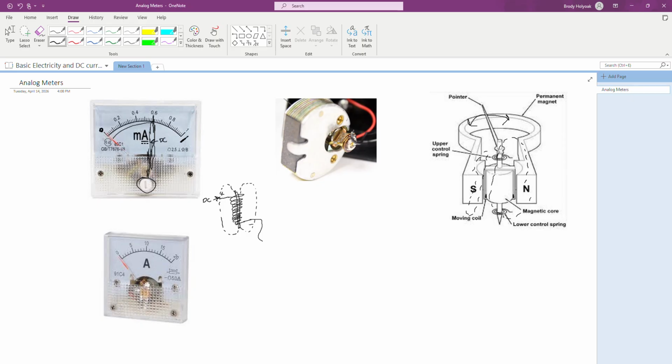And inside, it's kind of hard to see, but a lot of times they have a little post that sits right here to keep that needle from going too far. But what happens is physically we've stopped that needle, but if we keep putting more and more current through this, that magnetic field builds and builds and builds. And eventually this thing's going to try to rotate, and it's going to try to put the needle over here. But if there's a pin right here that stops it from spinning, eventually that needle or that arm, instead of looking like this, is going to start doing this. We're going to start bending things, and we're going to start changing how this works.